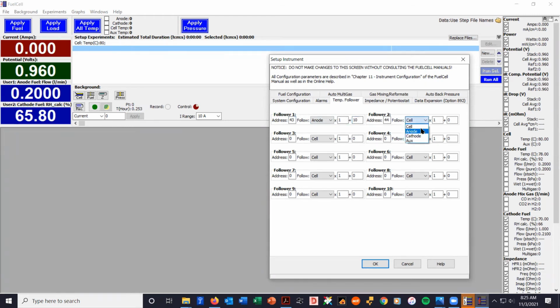And on the cathode, we run the cathode line at the same temperature as the cathode humidifier, but add 10. So if the humidifiers are both at 80 degrees centigrade, that would apply a temperature set point of 90 degrees centigrade to the anode and cathode.